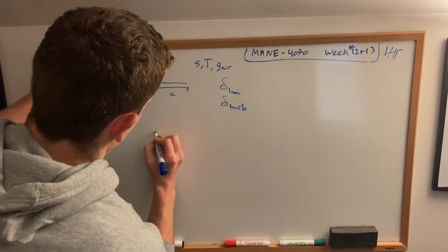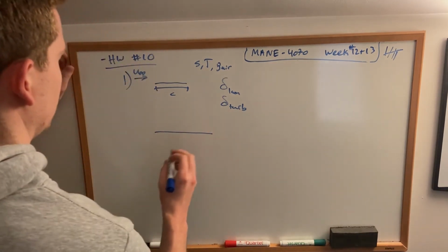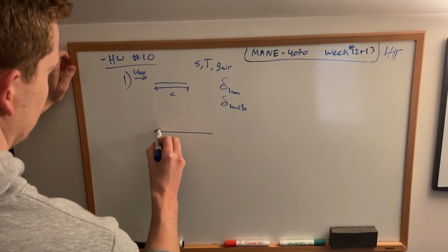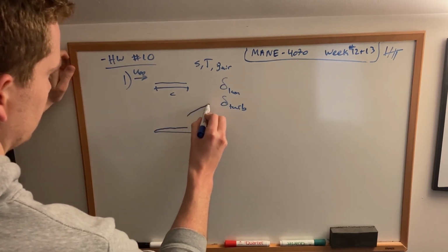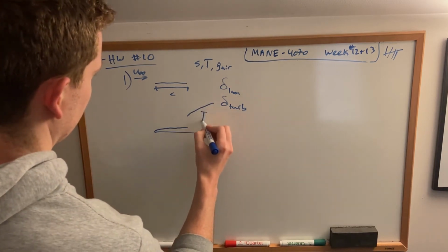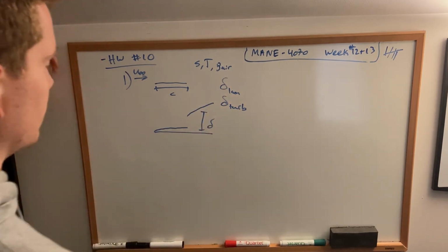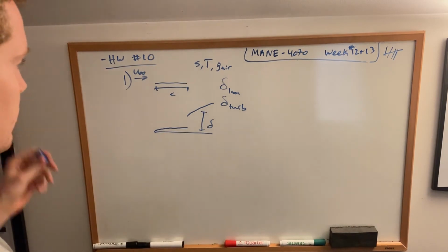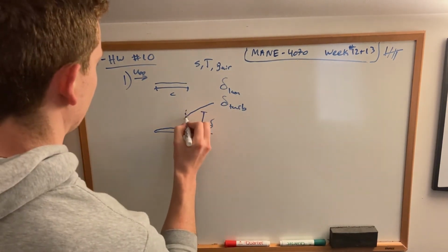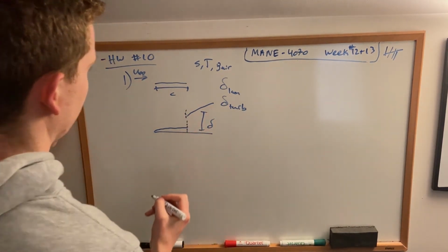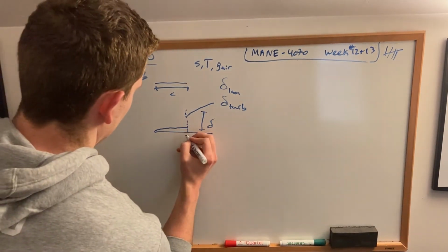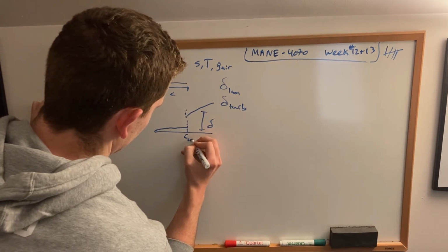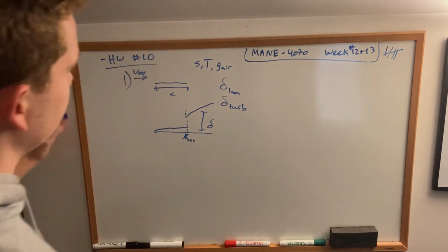So along your plate, the Reynolds number is going to increase. You can have some transition where you're in the laminar regime and then you jump to some turbulent regime, which would cause your delta to increase. So what you have to do is go through and find out where, or if, you hit the critical Reynolds number at some critical length, called X crit.